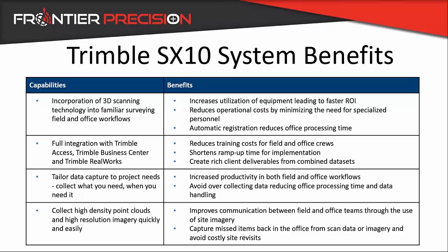With this product, you're setting up over a known point, or you're resecting, you're doing standard robotic operations, and the targeting registration process is eliminated. Full integration with TBC and Trimble Access, as well as Trimble Realworks. So again, we're using a familiar interface, so that reduces our training, it reduces our knowledge requirement, as well as tailoring our data capture to our project needs.